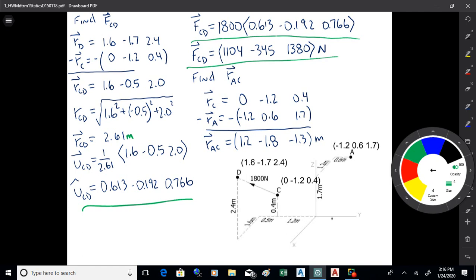Now that's just a position vector. You leave that as is. You do not want to unitize that, okay? Leave it as it is because the length of that vector affects the moment, right? The longer the wrench, the bigger the moment. So I know quite often we're used to unitizing those vectors, but in this case you don't because you want to leave the length in there, okay? So now we get a position vector.